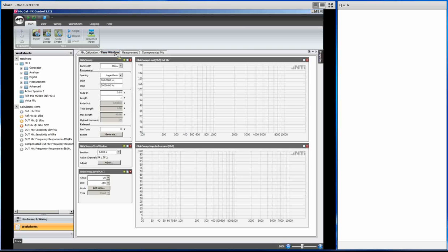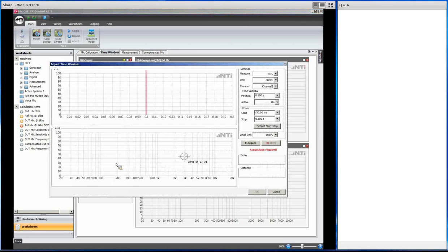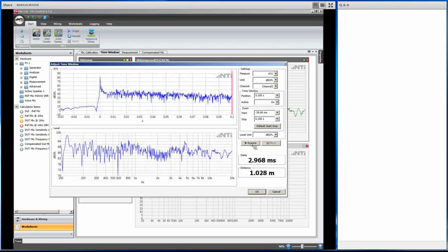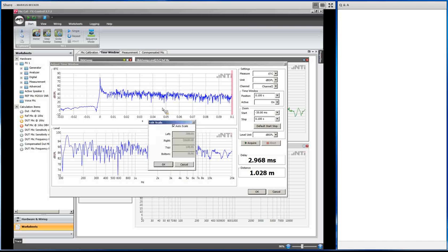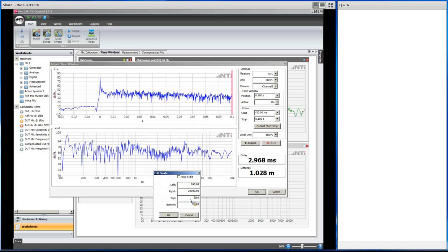And now I'm going to present you the solution how we can exclude the room reflections I have mentioned before. And for this purpose, we have a very nice assistant. This is this window. In here, I'm gonna just run one cycle. So you have heard the glide sweep test signal. You see up here the energy time curve of the incoming signal, and down here we see the frequency response that has been acquired from the reference microphone. Just adjust the scaling of that graph.